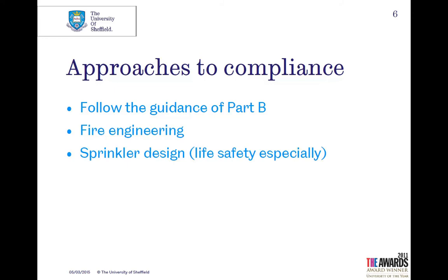Okay? If you've not got a fire escape, that's just bad design. But if you're doing a big art gallery, then it's probably quite realistic. You would have sprinklers and you would have fire engineering. So, it's okay to do that, but the important thing is just to be aware. And if you got to the end of your examination and, I don't know, one of the examiners said, well, you've got a huge distance between your fire escape stairs here, you would say, yeah, I know it's not as per the approved document. We'd have to rely on some life safety sprinklers. Just demonstrate that you're aware of that, and that's perfectly fine. Okay?